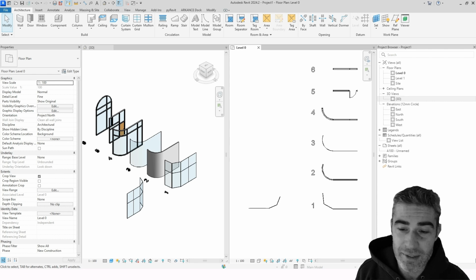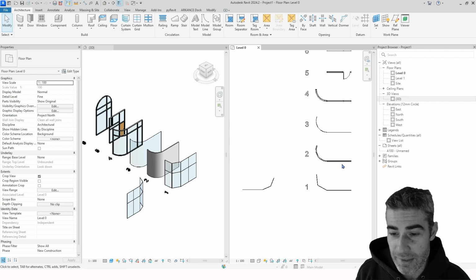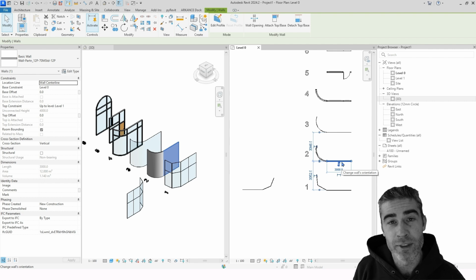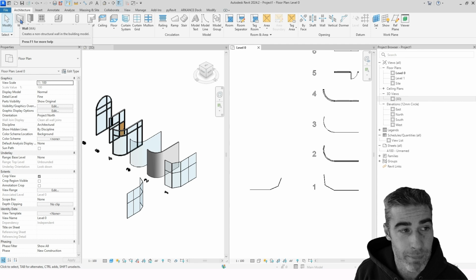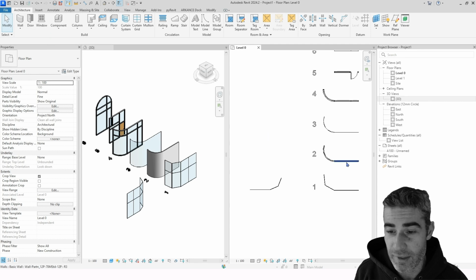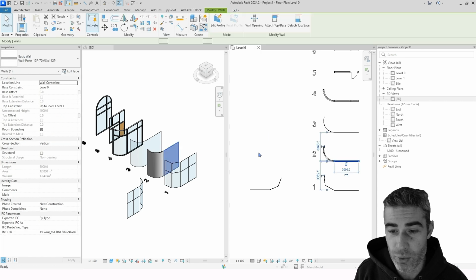So you can see here, when you go to create a wall, right now this is just a normal wall. There'll be a stud, some drywall on either side. You can see when I come to the Architecture tab and find your Wall tool, in this case I'm going to find a shortcut and just go Create Similar.